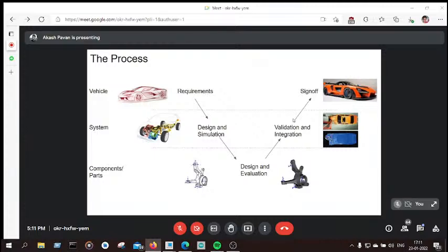Each OEM will have a design department. The design department will initially put up sketches, and then they will come up with renderings. So we get to visualize how the car will look. And once the design is finalized, then the vehicle architecture department comes in. The architecture department deals with the packaging aspects. In the packaging aspects of a car, we define the space for each of the components.